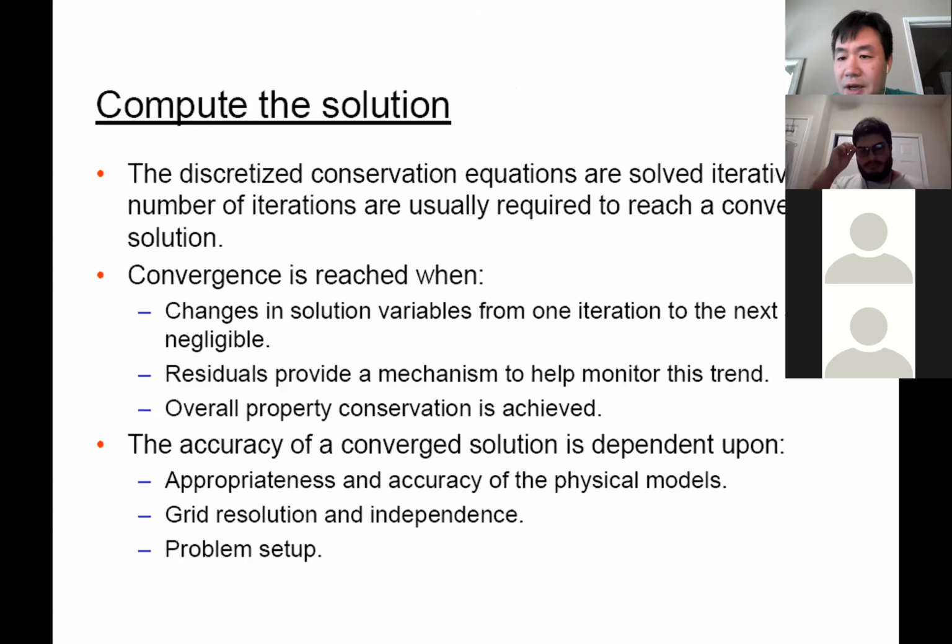The coarser it goes, the more inaccurate it is, right? If the grid spacing is big, then between every 2 points it's not linear. You are using linear approximations, and that's basically not true. So the finer it gets, the more accurate the solution, but the finer it goes,